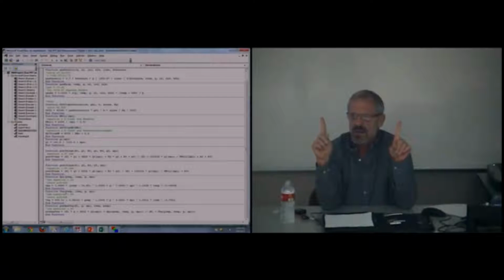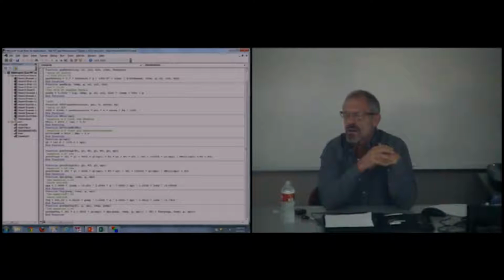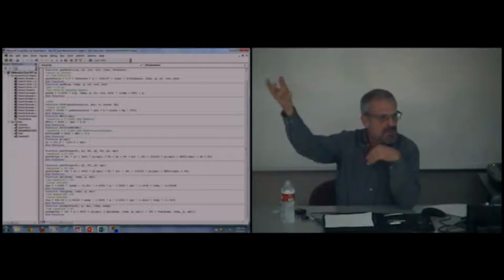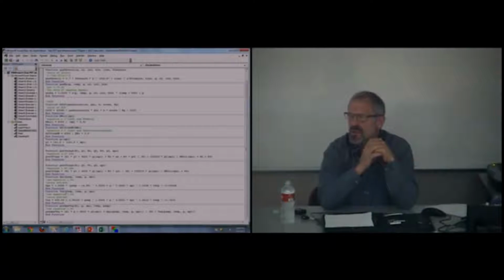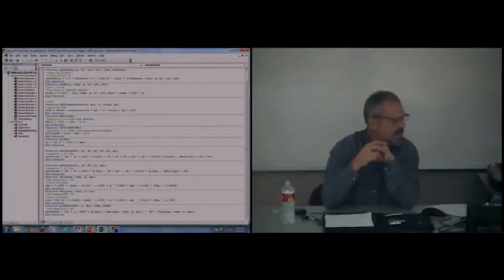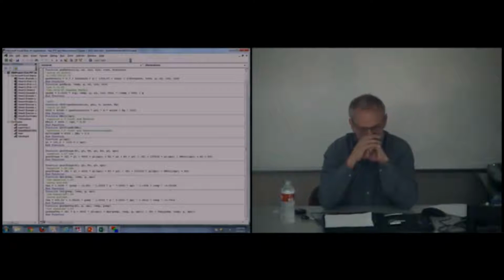Two different ways. If we have complete information, that would be the gas gravity from the first and second and third stage separator, the third stage separator being the stock tank, and we get by measuring the gas gravity of the vapors and the gas oil ratio for all those three. And that's on the spreadsheet when I go back to it.